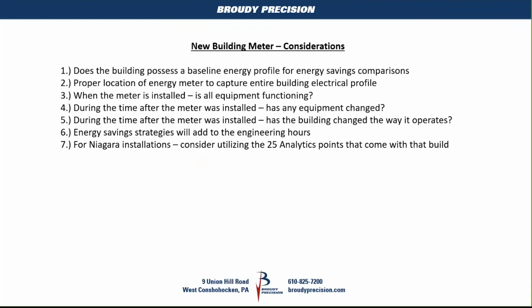That's what I mean when I said, is all the equipment functioning? I've had contractors go into buildings and they start getting air handlers working again, and that's going to make your energy bill go up. I mean, if that fan has not run in a year because nobody knew it was off on overload, and the building automation guys come in to capture it as a potential, now you're going to spend more money. And he didn't even know that the air handler was off. See that happen a lot.